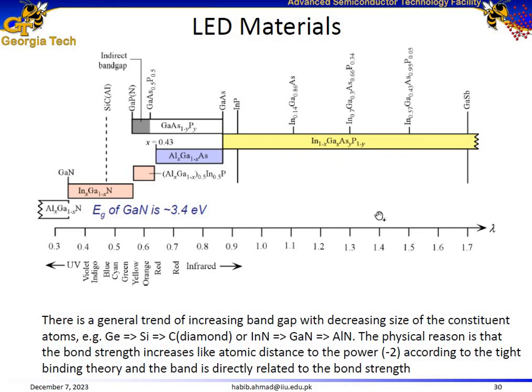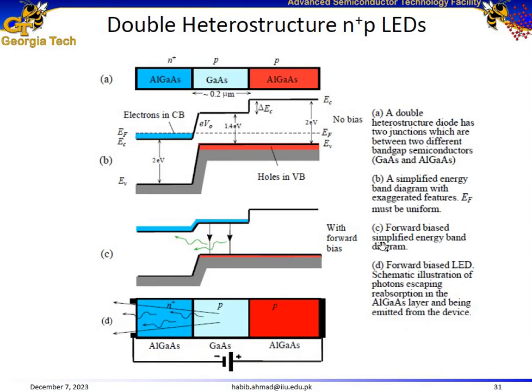And then this wavelength range around 1.4 micrometer, 1.5 micrometer actually is suitable for communication purposes. We previously talked about the basic N plus P light emitting diode configuration. The problem with that configuration is that it does not result in a high light intensity. There is low emission of light from the basic N plus P structure.